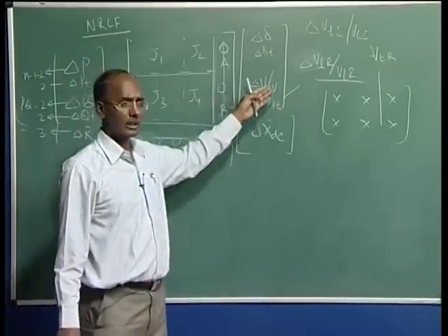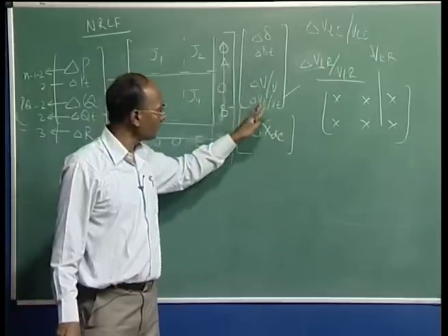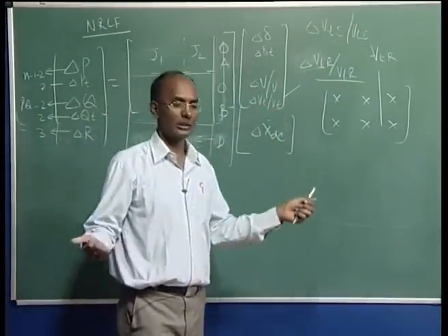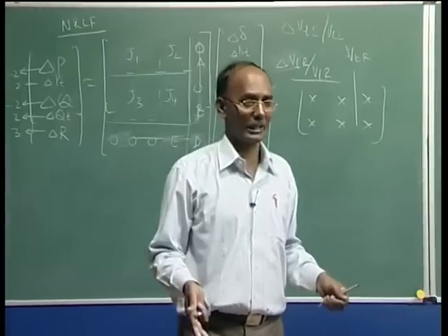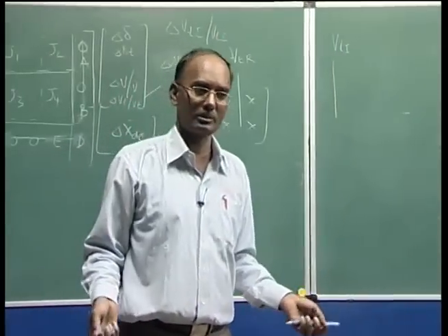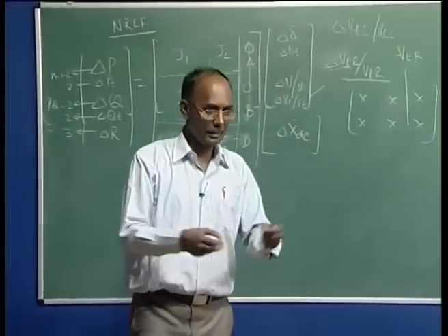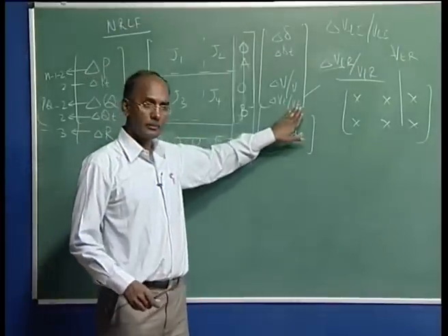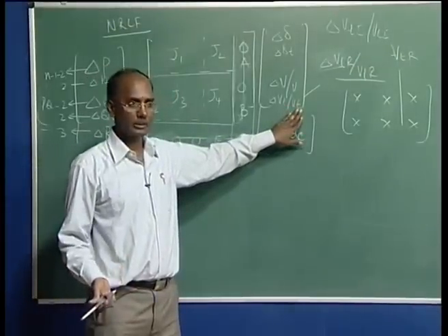This is similar to what we wrote earlier in the polar form. Same here, we are dividing again. This is the same reason, you remember, it gives the quadratic convergence. That is why we are dividing. If you are not dividing, you can still solve this power flow, no problem. Only it will take more iterations and sometimes it may not converge. The reason for dividing was already explained in the first lecture.